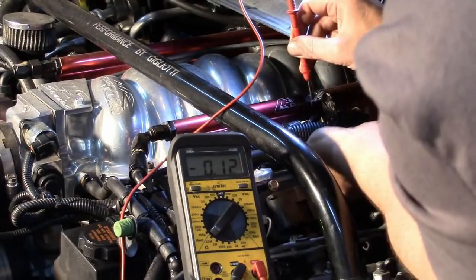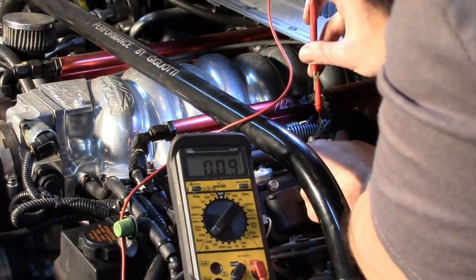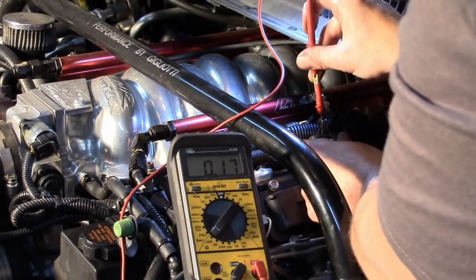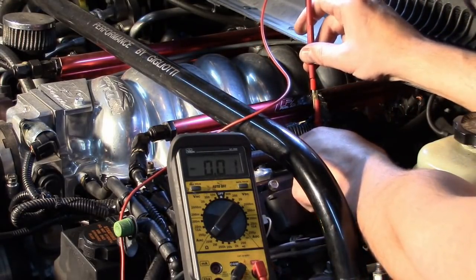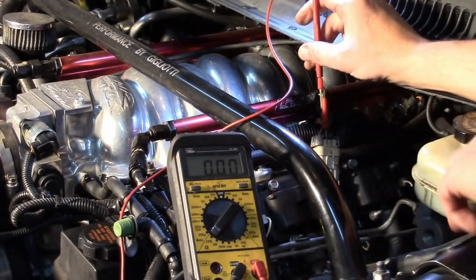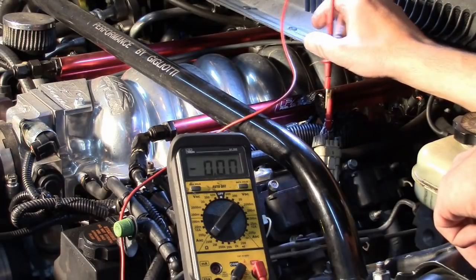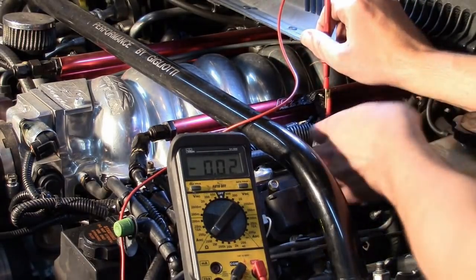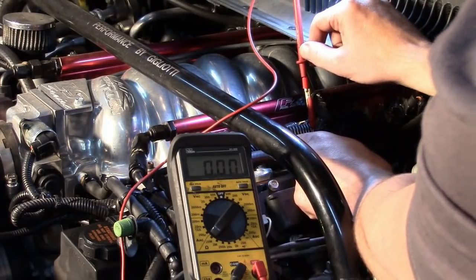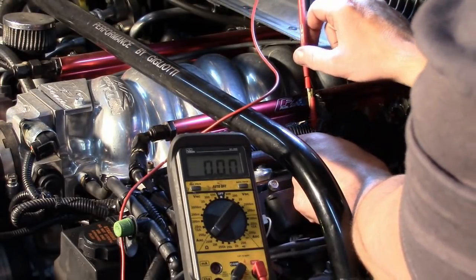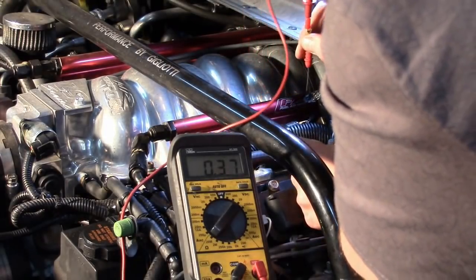Okay, so for the power, and again, I could look off that wiring diagram and know exactly. That's typically not how I do it. I can tell you there is a red wire here that I like as being the power feed for everything. So I'm going to back probe that wire, and I was wrong. Okay, so it is not the red wire. So hard to imagine that red wire would be a ground. I'm going to say most likely that red wire is going to be the control to one of the coils. Of course, I don't know which one, and don't care right now. I'm trying to find the power, but it's not the red.